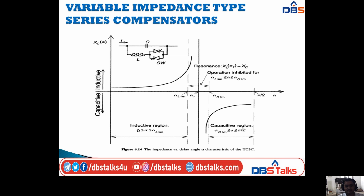This diagram gives the impedance versus delay angle alpha characteristic of the TCSC. Here I am taking the circuit arrangement, the basic general scheme of the TCSC. This is the connection diagram, and based on this diagram I am taking the impedance versus delay angle characteristics of the TCSC. In the characteristic diagram, the upper waveform gives the inductive region of this TCSC, and the lower one gives the capacitive characteristic of the TCSC.